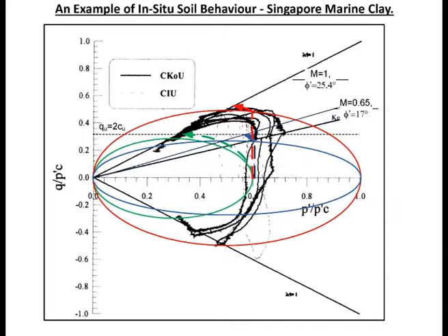And you are able to detect that in fact the soil looks as if it is lightly over-consolidated soil. But if you don't sample the soil very well, if the soil is completely disturbed during the sampling, in fact it looks like an under-consolidated soil, because in the process of sampling, you shear the soil, you load the soil. The soil has gone through one triaxial compression and unloading. So you already generated excess pore pressure inside. The soil is completely remolded. It has got excess pore pressure. So you check out the excess pore water pressure and it looks to you as if the soil is still consolidating.